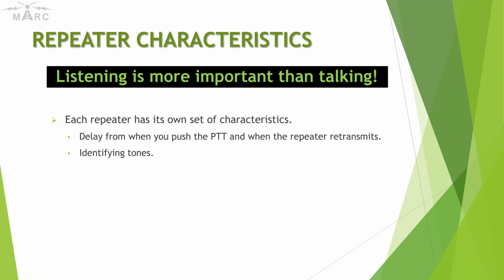Good stuff. Okay, let's get back to the personality of a repeater. Again, we've been talking about this in the nets. A lot of people aren't listening to what the repeater is doing. They'll transmit, and as soon as they hit that PTT button, they'll start talking, and what they don't understand is the repeater takes a half a second to sync everything up, okay? Especially with repeaters that are tied together, like on the intertie, it takes a few seconds for them to all sync up, okay?